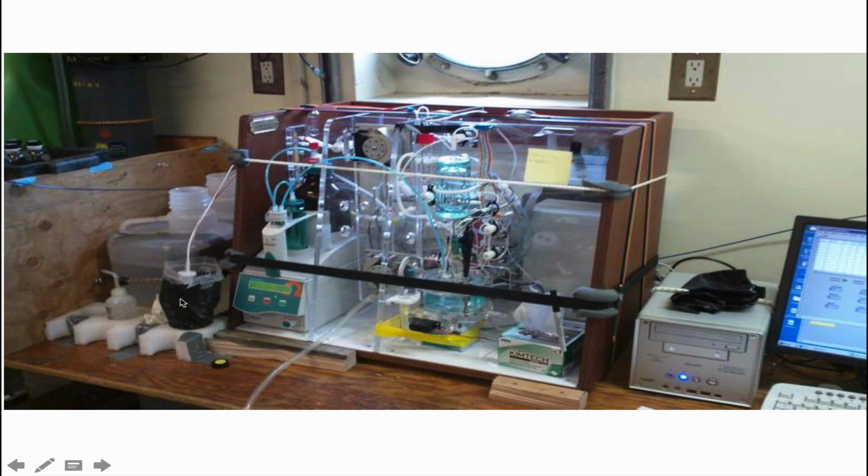And it has a bunch of components. This is where the sample bottle goes. That sample tube goes back over here into this pump. And somewhere in this pile of glass, right in here, there's a reaction chamber. We're going to react acid with the seawater samples. And then that gas that's produced, which is CO2, is going to be transferred down here into our coulometer. We're going to have a computer that's going to monitor these reactions. And this device is capable of measuring the total concentration of CO2 much better than 0.1%. So let's dig in a little bit and see how this instrument works.